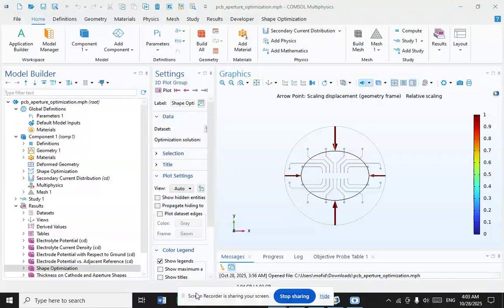Electroplating, also known as electrochemical deposition or electrodeposition, is a process for producing a metal coating on a solid substrate through the reduction of cations of the metal by means of direct electric current. The part to be coated acts as the cathode, or negative electrode, of an electrolytic cell.